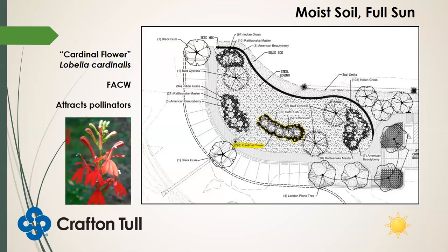And what percentage coverage do you see inside the bioretention area? I'm hoping full coverage. We'll see. It might require some maintenance and some follow-up to make sure that happens. I've seen that many beds will stay dry for extended periods. Yeah, that is true. I mean, a well-designed rain garden will drain within 48 hours.